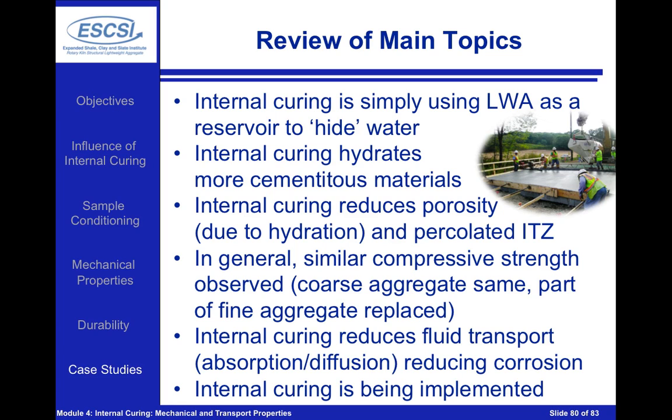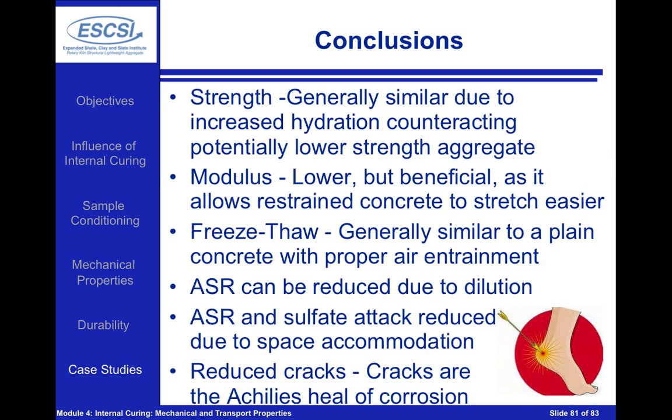The final takeaway is that internal curing is being implemented, and when it's being implemented on bridge decks, very positive things are being noticed with a reduction in the overall cracks that are forming in those systems, and very similar, if not improved, transport and strength properties are occurring in those cases. So in general, we're getting a similar strength because we're increasing hydration.